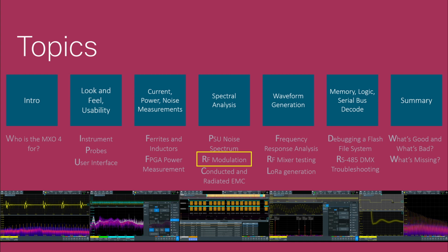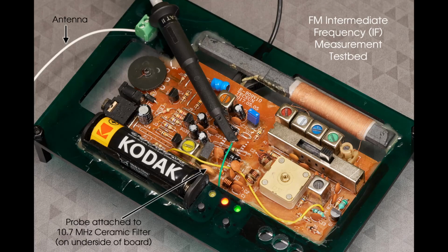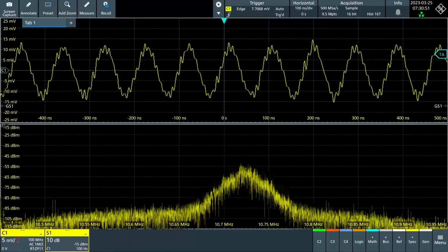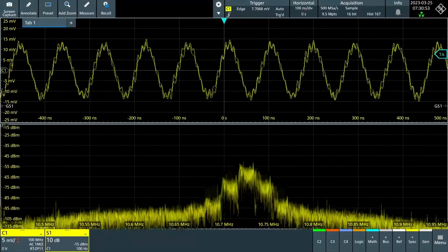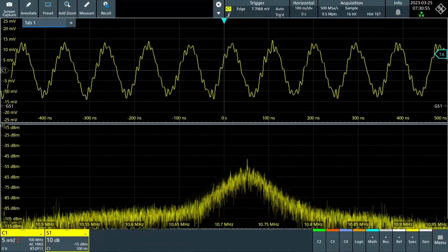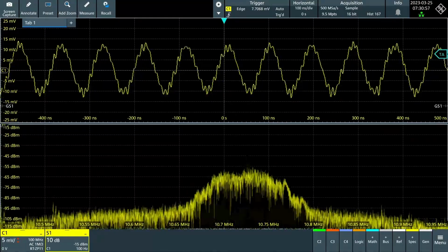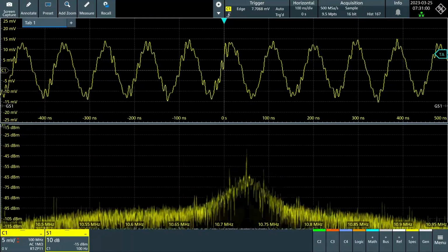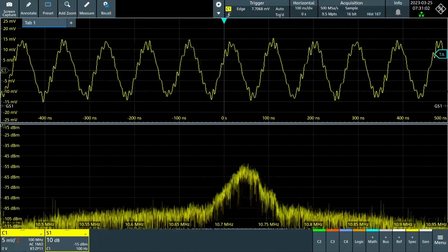connected it up to the 10.7 MHz intermediate frequency output taken from an FM radio. The results were impressive. The span here is set to 500 kHz. The fast responding display is comparable to software-defined radio displays, but many SDRs won't work at such low frequencies.